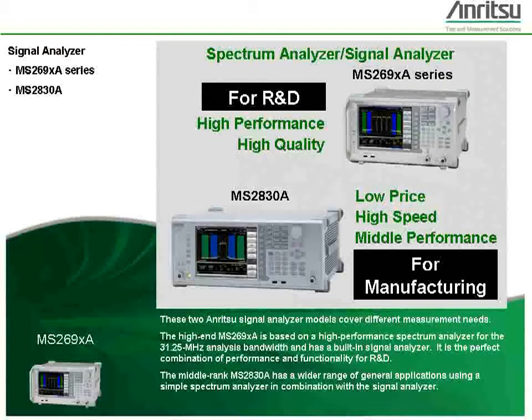These two Anritsu signal analyzer models cover different measurement needs. The high-end MS2690xA is based on a high-performance spectrum analyzer for the 31.25 MHz analysis bandwidth and has a built-in signal analyzer. It's the perfect combination of performance and functionality for R&D. The middle rank MS2830A has a wider range of general applications using a simple spectrum analyzer in combination with the